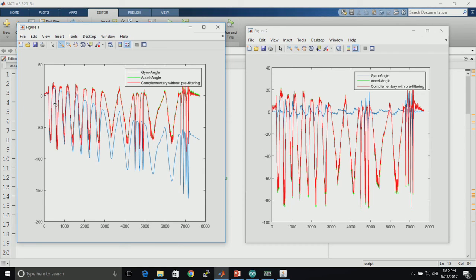Here we can see the value of drift, where the angle computed from your gyroscope is drifting in a way where we get peaks from 0 to around 60 degrees, but at sample number 7000 the angle value starts from 60 degrees and goes to around 120 degrees. So here we can see the gradient in which there is the drift.